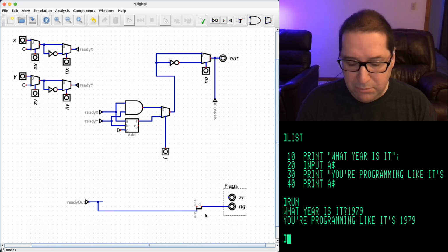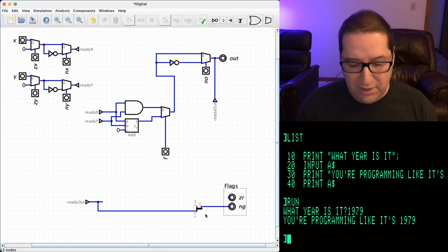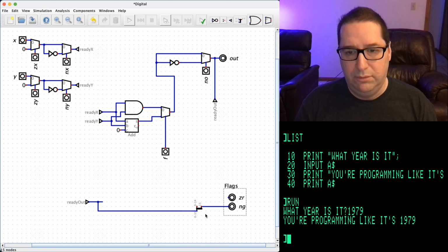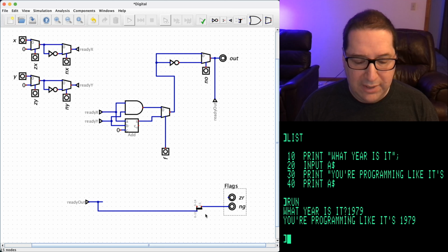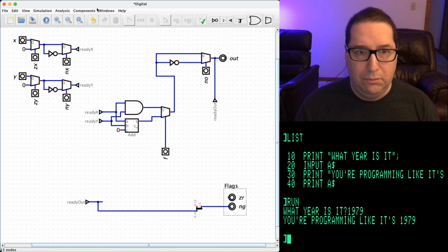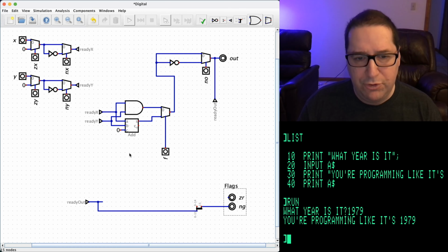So we've got a number of bits coming in, in our 2's complement representation. If it's all zeros, if every bit is 0, then this flag is high, and in every other case, this flag is low. So we actually made a component that will deal with this. We made an OR 8-way gate. Sadly, this is 16 wires, not 8. So we will have to split this out a bit.